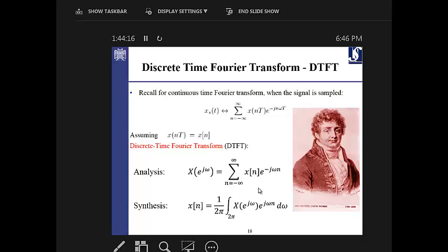Yes, please. I have a question about the spectrogram that you showed in the last lecture. You showed the frequency spectrum over time, but we can take the spectrum from a single point, right? So do we take a window and then take the transformation? Exactly. A spectrogram is the time evolved version of DFT. So you take the DFT of every time frame of the signal, and then you evolve over time. Go to the next frame, take that frame just in that period of time, take the DFT of that and represent it.